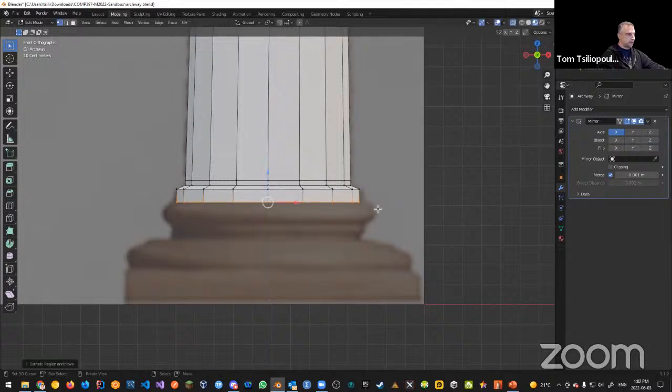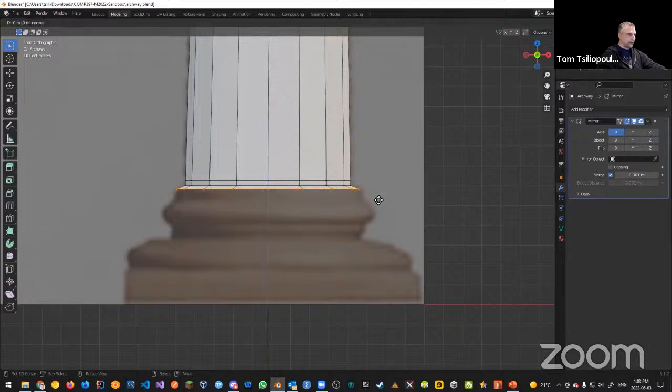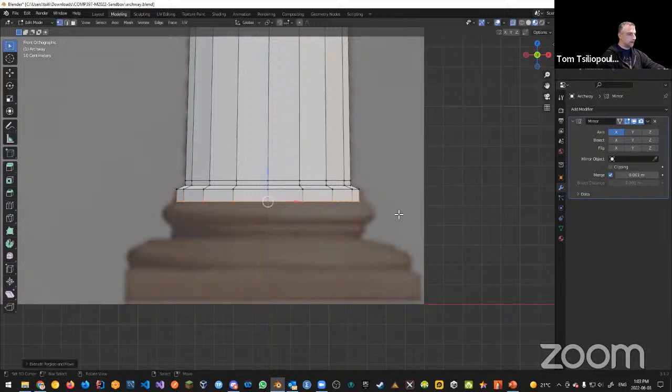Again, it's not going to be perfect, but don't worry about that. If I was to do the S key here, you can see that this is no good, right? Because I need a crease to help me out. So let's undo that extrusion. So if I extrude, I want to kind of extrude twice. I want to extrude down to here, right, as an example. And then I want to extrude again when I come down here. So I want to come down to this point and then click extrude again and then press enter. So extrude and then enter duplicates my geometry.